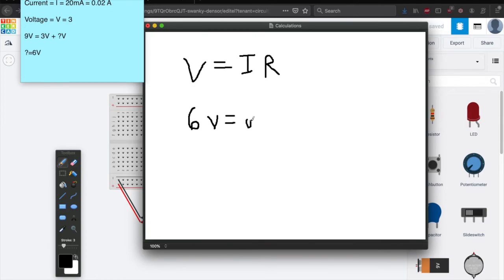So we'll call it 0.02 times, which is that little dot here, the resistance. Now we have an algebraic equation with only one variable, and we can really easily do this math. In order to solve, resistance is just going to be V over I, which is the reverse form of that equation that you can use to solve resistance if you jiggle it around a little.